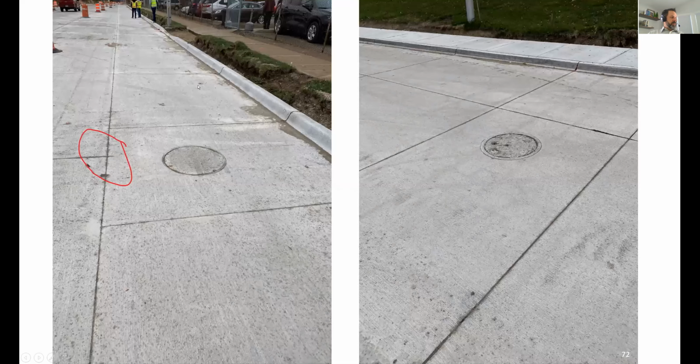Here's some other details from some projects we've looked at in the past. One where we've got a nice transverse joint spacing, but they did a square block out or box out around this casting and then oversawed slightly into it. I feel that this is going to continue cracking. Now, this is fairly recently placed and hasn't cracked yet.